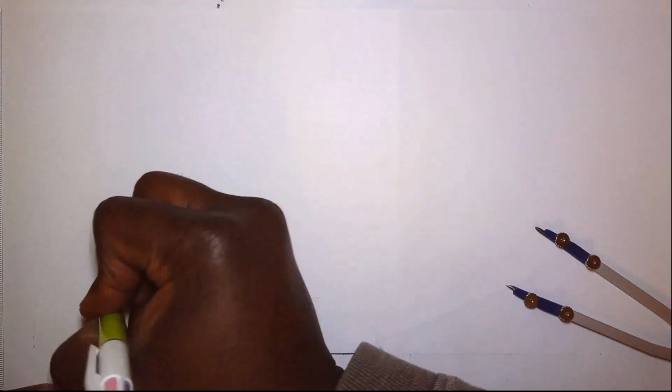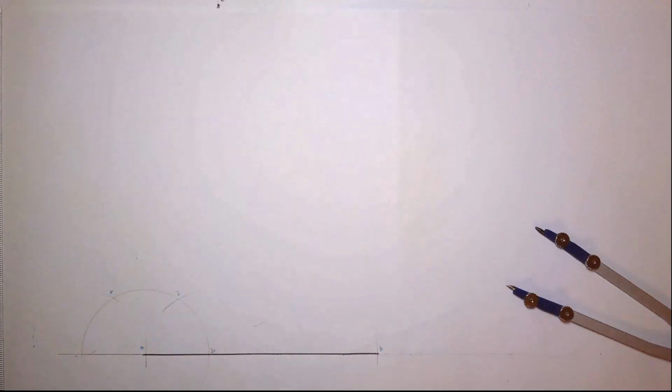Okay, so let's say that's from 2 to A, and I'm going to scribe an arc to cut the semicircle, and I'm going to do likewise. Then at 1, make sure it's open to A, and I'm going to scribe to cut the semicircle. So this is what some people tend to do. So let's call this intersection 3. Let's call this intersection 4.